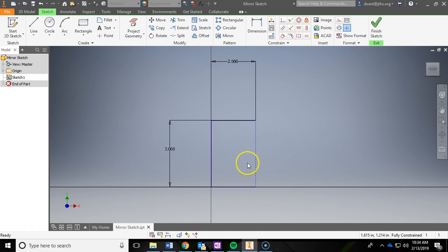Okay, so then let's draw in those circles. I'm going to go Circle Tool. I'm just going to draw somewhere in this vicinity and draw a circle. Then I'm going to reference that center point from the existing circle and draw another one right there. So now this one is aligned with that one because I referenced that center. Hit escape to get out of the circle tool.